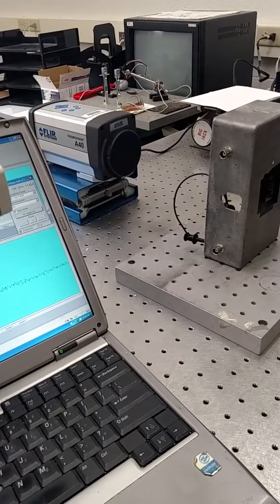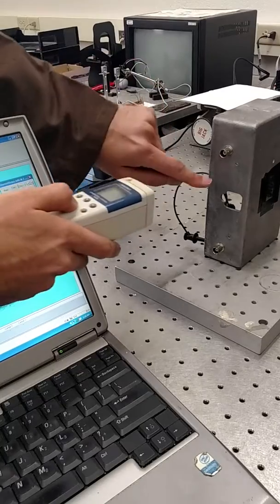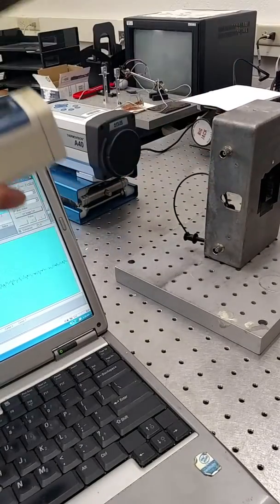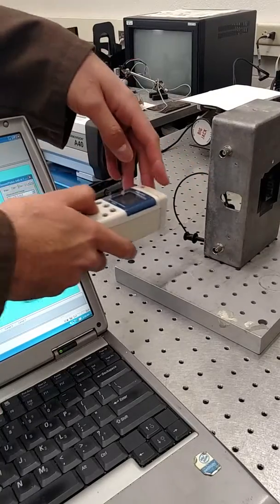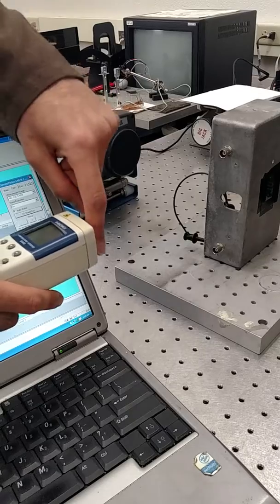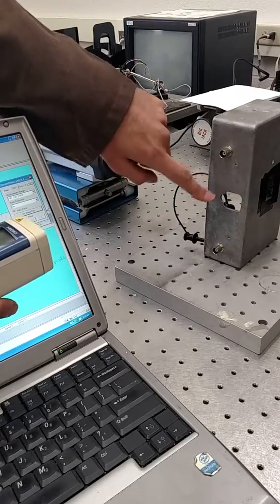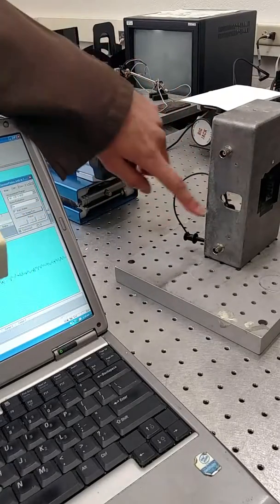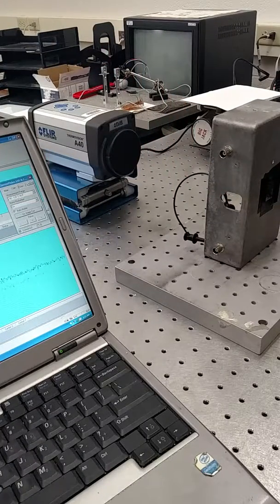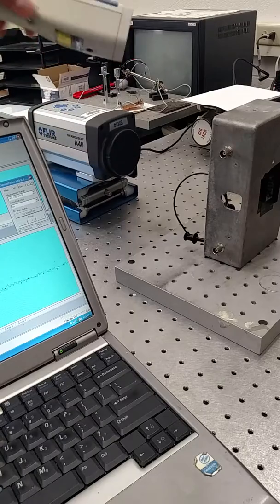It's sort of deceptive, because when you get really close, there are two lasers that come out to show you where it's measuring, and the two lasers get on top of each other. You think, hey, I'm measuring that point exactly, but that's wrong. The minimum laser size you should have, because the two lasers come out from here and here, is 3 millimeters. I think it says something in the manual about it. I don't remember because I don't use it, but just know about this. You can actually use it if you want to measure a single temperature.